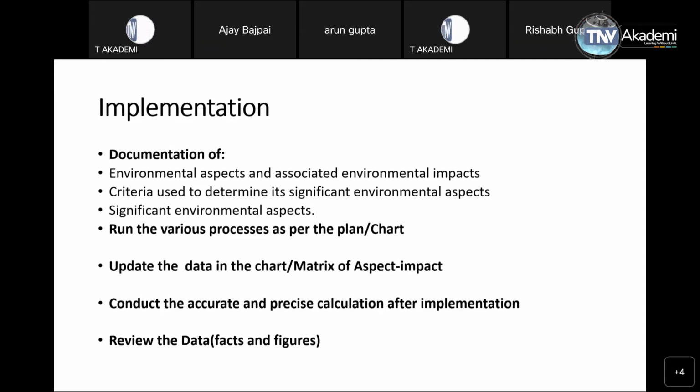This chart data needs to be updated on a continual improvement path, as and when we notice some changes are required, as and when we see that some values are going out of control or reaching the limits. The requirement is to have 75 dB in an industrial state of Haryana for a DG set. So the moment we reach a level sometimes of 73, 74, lights should be on alert mode, that yes, we are required to do some updation into products, processes, charts, calculation, training, oiling, maintenance procedure. So this updation of data in this chart is very, very important.